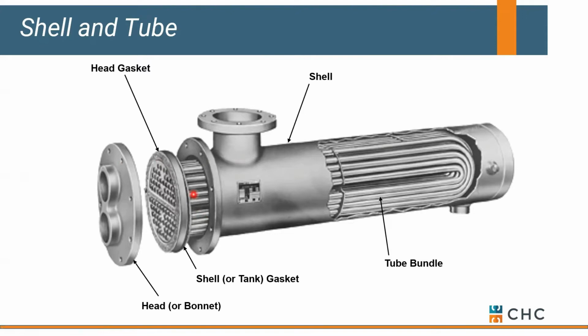That's pretty important. The other thing is you tend to have quite a bit of surface area on these. So if you have a tube that ruptures or fails, you'll see a lot of facility guys put a dowel in the tube that's affected. They'll put a dowel on both the incoming and leaving tube, and then they'll put it back into service. There's nothing wrong with doing that. And you'll typically dowel up a number of tubes until you start to notice a lack of performance or heat exchange. And in that case, it's probably time to replace the tube bundle.